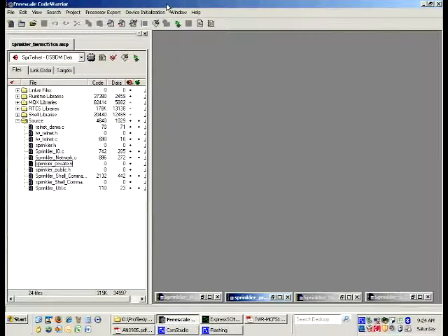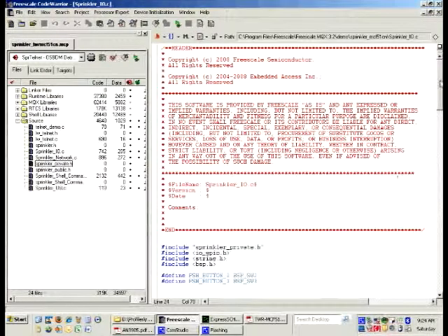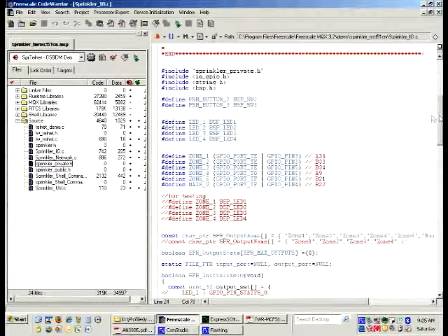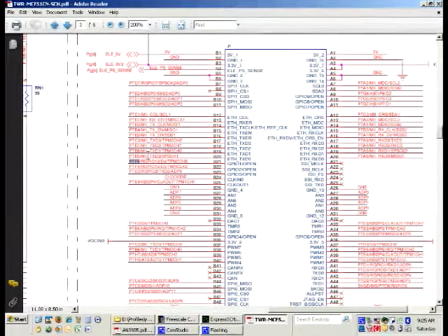So this is the software for the sprinkler system. It's based on the MQX security demo, and the first file is sprinkler.io.c, and the first thing that I'm doing in this file is telling it what signals from the microcontroller are used to turn on and off the zones. The way I picked these signals is, I looked at the schematics for the 51CN microcontroller module, and I found some signals that weren't really being used for anything.